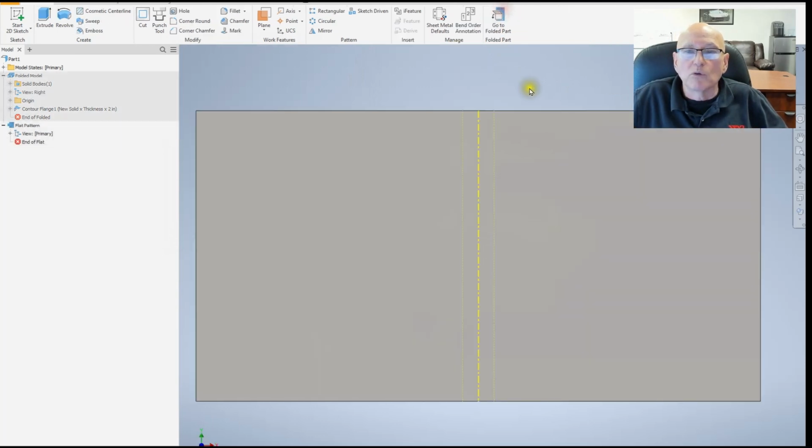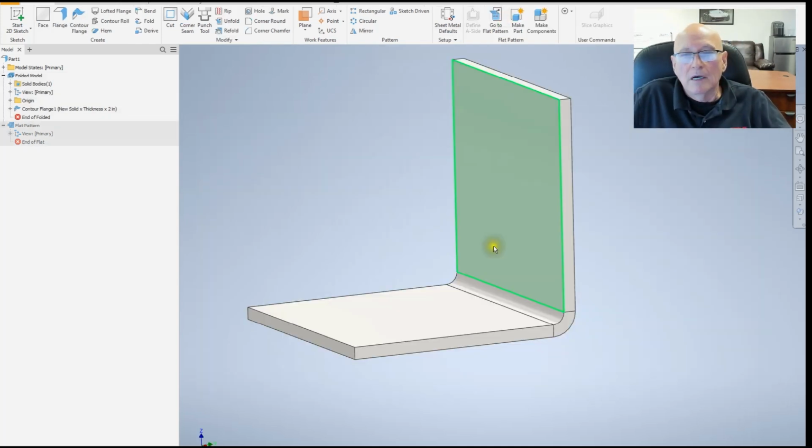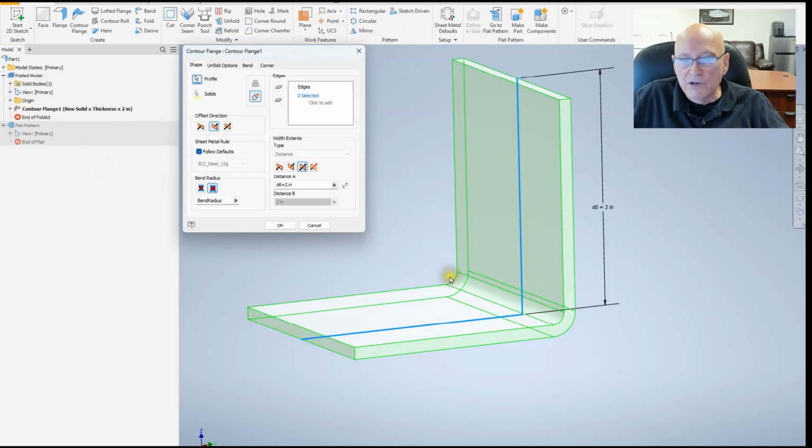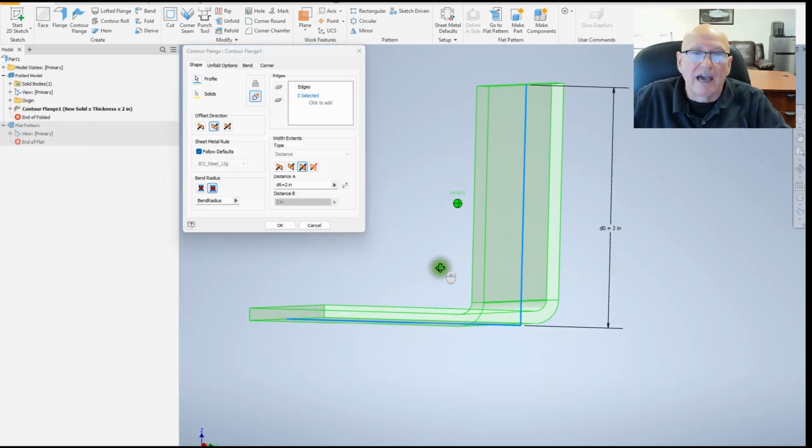Now look what happens when we go to measure it. 3.81. That's over a 200 thou difference, 0.2 of an inch, or 5 millimeters, just because we changed which side we were measuring on. I'm just showing you that because, believe it or not, it has happened here. So you always want to do your profile in your CAD program outside leg to outside leg.